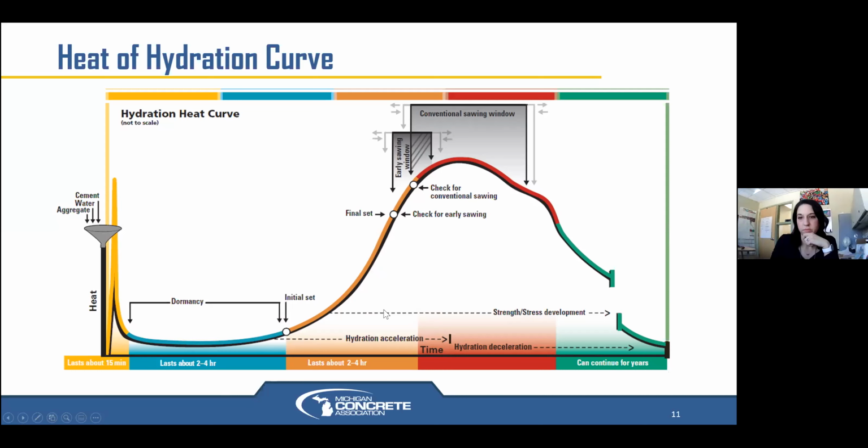We've got a couple of agencies in Michigan which still prefer that as their option of not obtaining load transfer, but extending the amount of time before roughness comes into play and faulting occurs due to heavy loads, because the skewed transverse joints, being on an angle, have it such that the truck tires aren't all hitting that joint at the exact same time. Only half of that axle is really crossing the joint before the other half. So skewed transverse joints have worked.